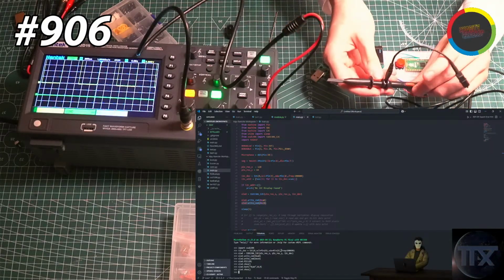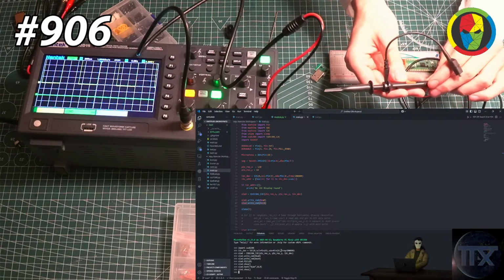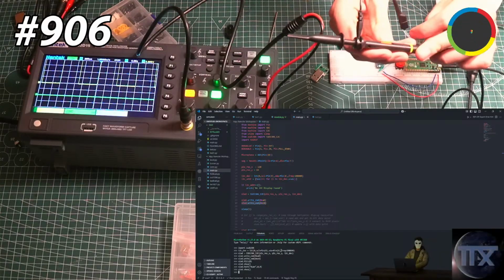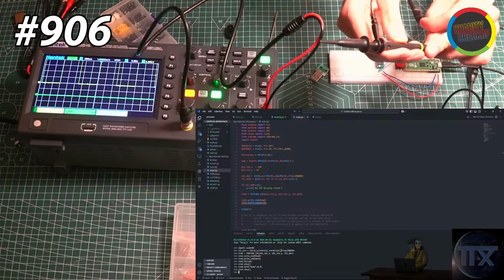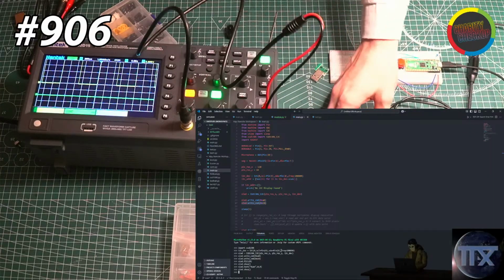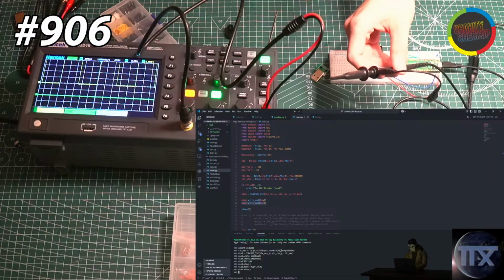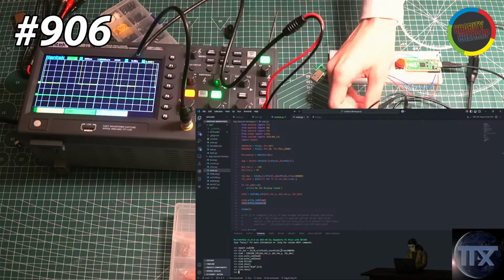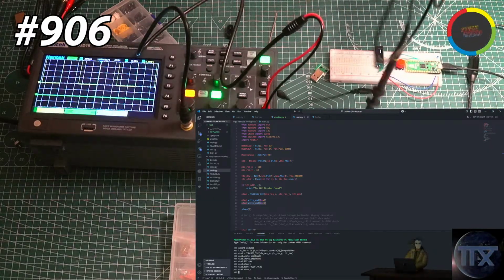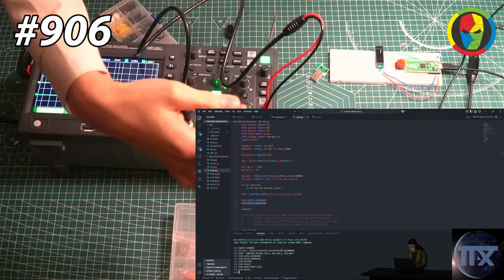Okay, so I only have one of the proper probes. I have two of the improper. It also has a mode switch on one side that says 1x or 10x. Those are your levels, so changing them changes the reading on the scope. You usually want to tell the scope if you changed it from 1x to 10x, in case you're reading a higher voltage, because the scope will also tell you the voltage amount as long as those two are matched.